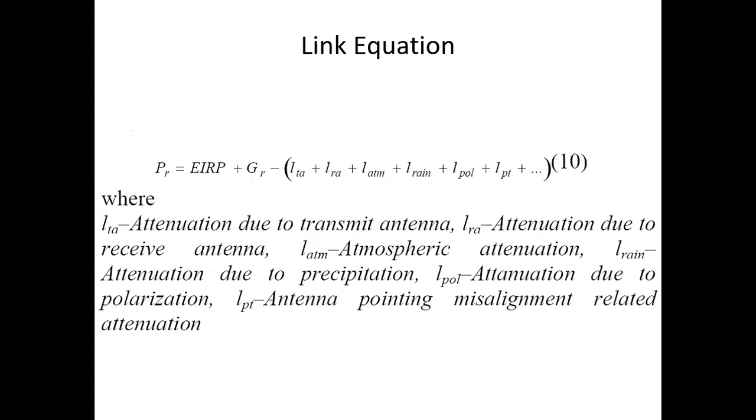Raindrops at ordinary frequencies don't hamper that much, but at higher microwave frequencies, rain is a severe problem, because the raindrop and the wavelength have similar dimensions. Both are in the order of centimeters.